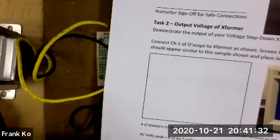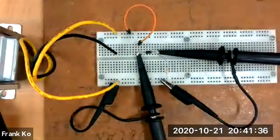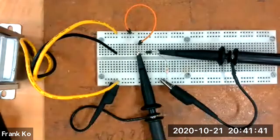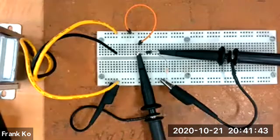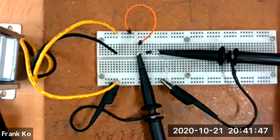Let's see, AC volts is measured on your DMM. So what did you measure on your digital multimeter? That's a good thing to do. Let's go ahead, take your digital multimeter, turn it on, read AC voltage.